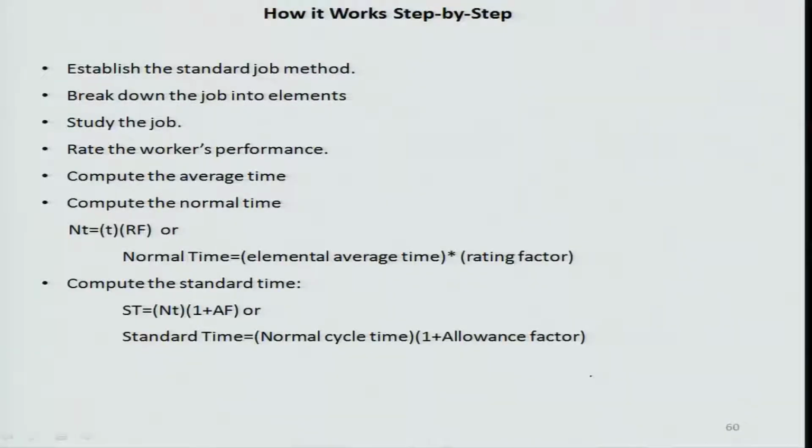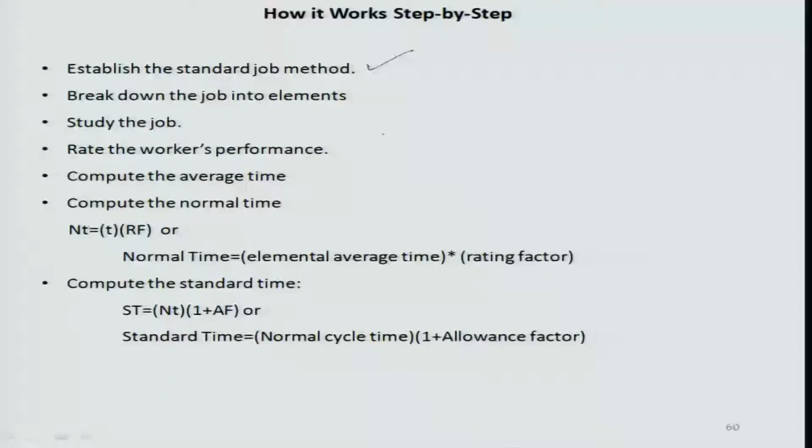So, how are time studies carried out? Typically you establish a standard job method first. You have been doing that using so many cycle charts, so many different forms of representation, outline charts, etc., which you did in the first module of the last lecture. Then you break down the jobs into elements, study the jobs properly, and rate the workers' performance.